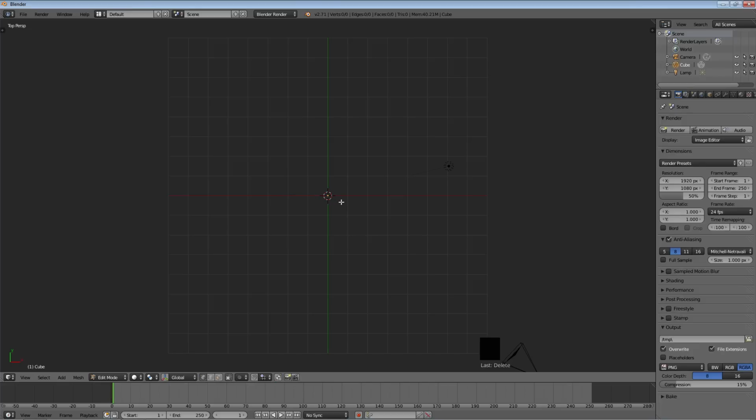Now, what I want you to do is draw a mesh. Hit 7 on the numpad to make sure you're in this perfect view. It makes it a lot easier to draw. And then what you can do is hold down Control and draw point by point a simple shape. And if you keep holding down Control and don't let go of Control, when you're left clicking here, it'll connect the points with these lines automatically as you draw them.